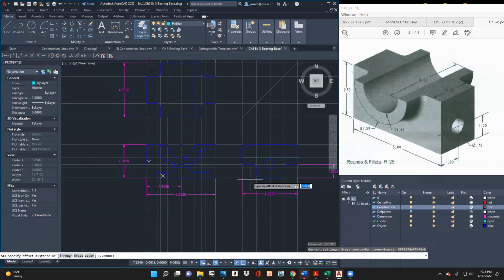So we're going to do it from the bottom. It's 1 inch, so I'm going to type in 1 is my distance. This is the object here, and go 1. Try that again. Offset distance, enter. Select the object, and so why is that? Oh, that's right. I'm sorry. So that line would actually be 3/4. That's right. So enter. Do it one more time. The through.